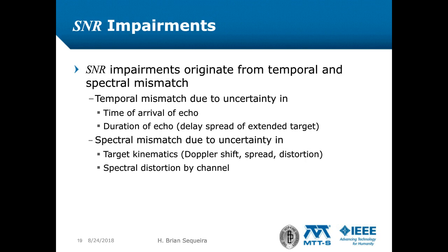Suppose the transmitted signal is a pulse carrier whose frequency is constant. The spectrum of that signal is a sin x over x, or sinc function, centered at the carrier frequency. An ideal filter would mimic the spectrum of that signal by providing gain in proportion to the spectral lobes of the sinc function and having zero gain at the signal's nulls. In this way, the filter rejects noise where the echo level is low or zero.